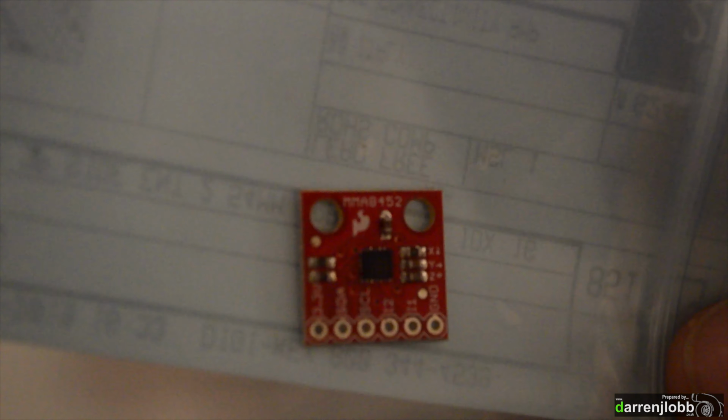You'll see on top of the board you've got an X and Y with an arrow pointing in two different directions on the right hand side there. That is the direction in which the sensor is mounted for your roll and the pitch angle. So it depends on how you have got this board mounted in your tractor as to which of the headers you want to use to mount this onto the PCB. So if you've got the PCB mounted flat with the axis of the tractor, then you'll want to mount it with the straight headers, so that this board is level with the axle of the tractor.